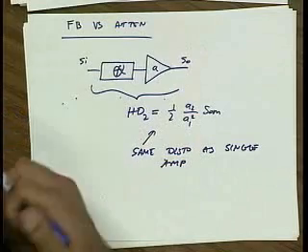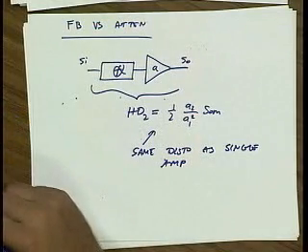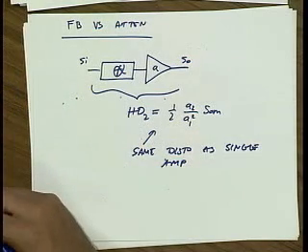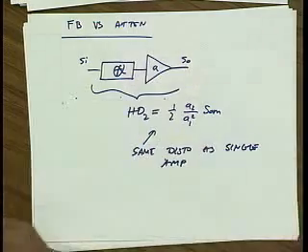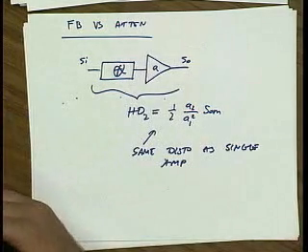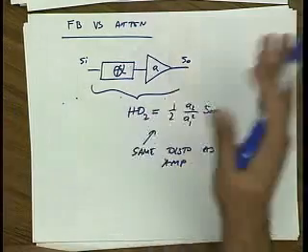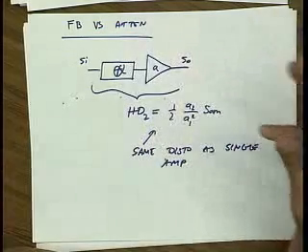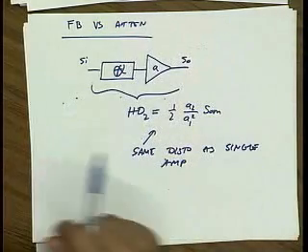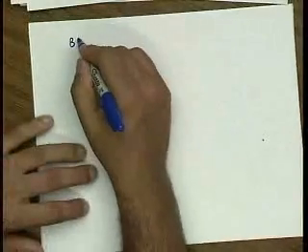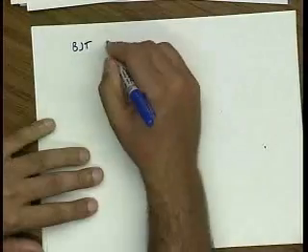Because the whole reason why we use feedback is not just because it improves distortion, but also because it makes our gain insensitive to process and temperature. So feedback has other benefits as well. But you'll note that all those benefits really stem from the same source. Process variation looks like extra error being generated, and the feedback rejects it. Temperature variation looks like an error signal being generated, and the feedback also rejects it. Feedback is good.